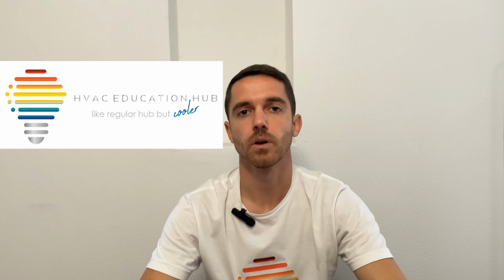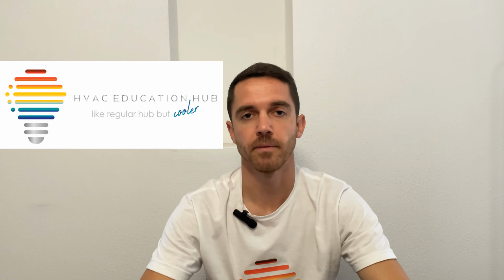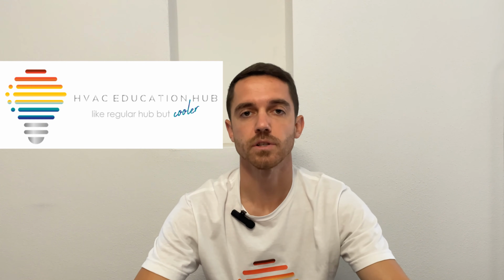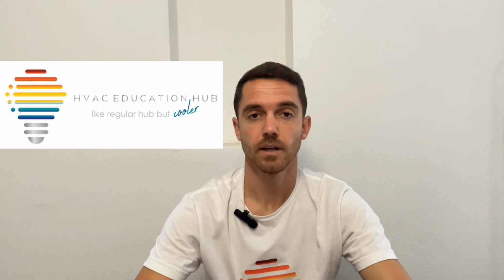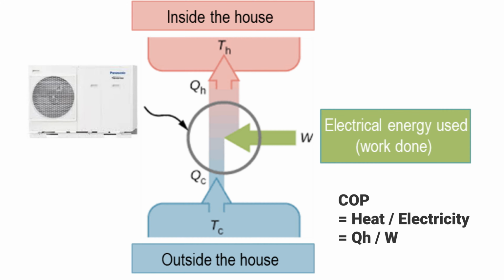In this episode, we'll cover what COP is, what the efficiency of heat pumps is, and what the main variables are to calculate it. COP means coefficient of performance, and in a heat pump or refrigerant system, it is a ratio of useful heating provided to work or energy required. It means it is the ratio of heating delivered to our system by the electricity used to produce this heating. This electricity is mainly from the compressor, as the compressor is the heart of the refrigerant system.